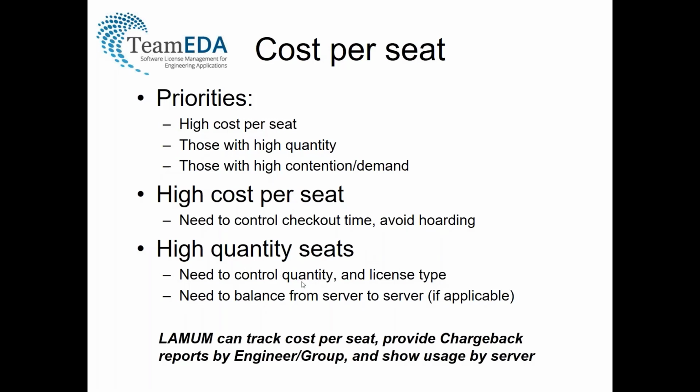A LAN is useful if all of your engineers are in one time zone. If you have your engineers in multiple time zones across multiple regions of the world, perhaps, then the WAN begins to look more desirable, but it is more expensive too. So you need to do some trade-off analysis between node-locked, LAN, and WAN to determine what's the best mix.